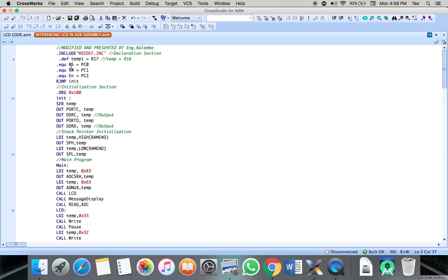All this here, what we're just doing is giving the name and declaring to which port that is. So reset is connected to port C0. Write is connected to port C1, and the enable, which is actually the logic enable, is connected to port C2.